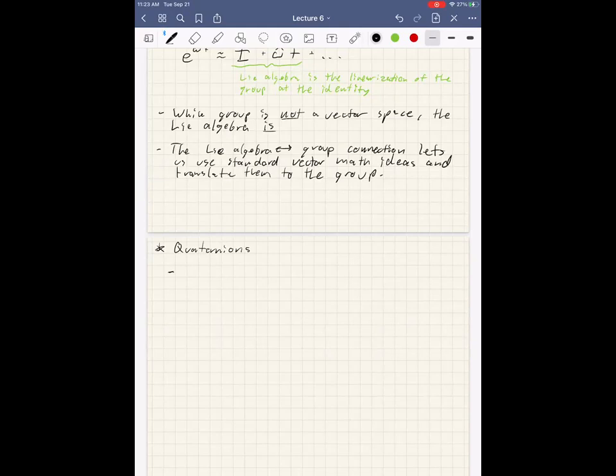Quaternions are super useful. Who's used quaternions before? Show of hands. Pretty much everybody. Awesome. They're basically the standard rotation representation any time you need to do things numerically involving dynamics, simulation, or computer graphics. So you've got to know about them, and we're going to make you do this on the next homework. They have no singularities like rotation matrices, which is good. They also have fewer elements, so they're more compact, more efficient, and easier to deal with because you don't have to worry about so many constraints. That's why they're popular.